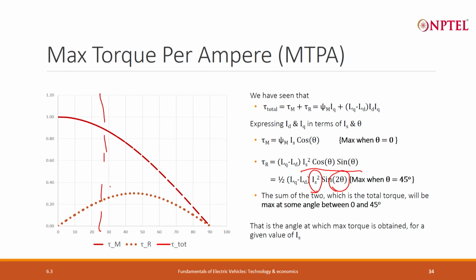So, if I plot the total torque curve again, the optimum angle will move closer to 0, because the weightage of the magnetic torque is higher when the current is lower. Are you able to visualize that? And you can visualize the same thing in the converse direction.